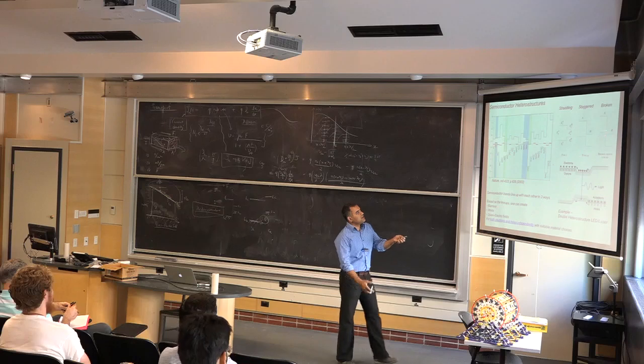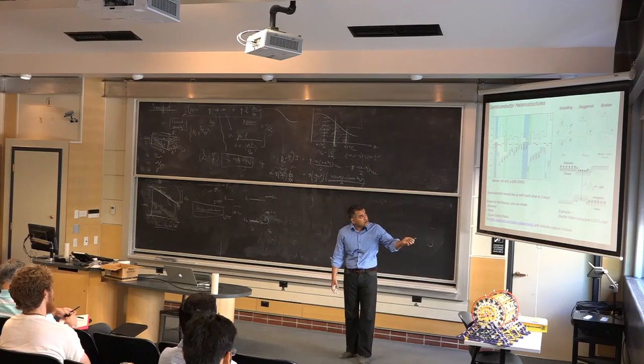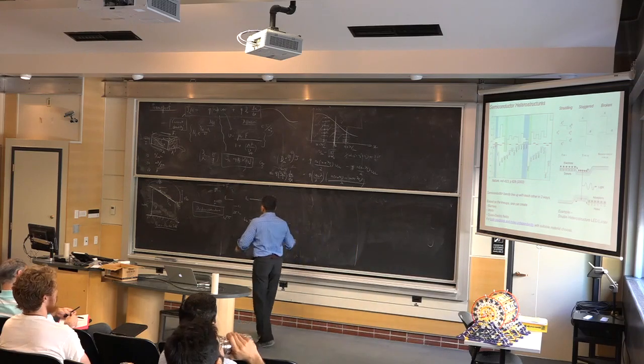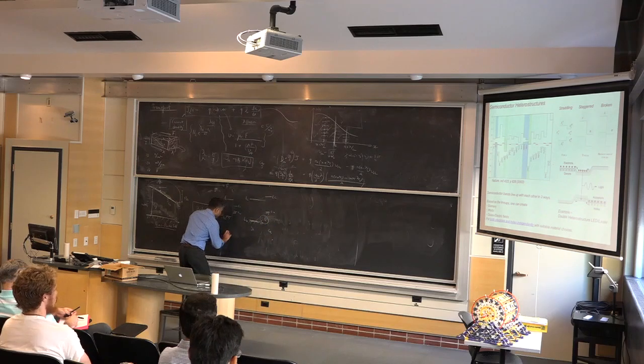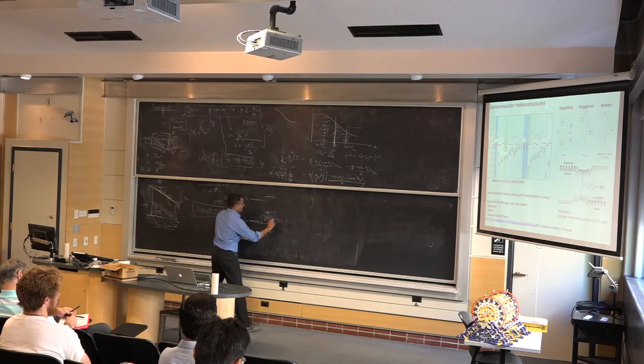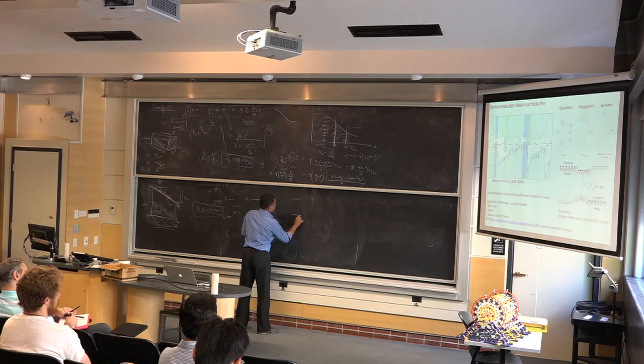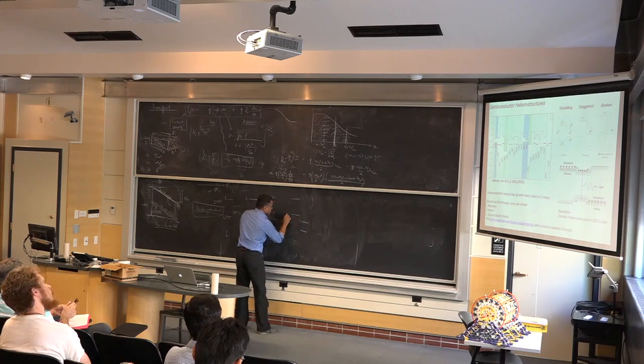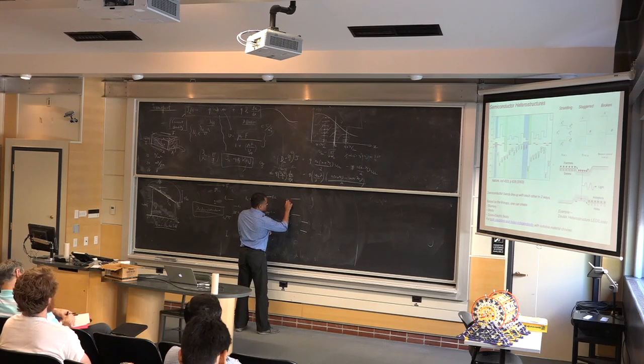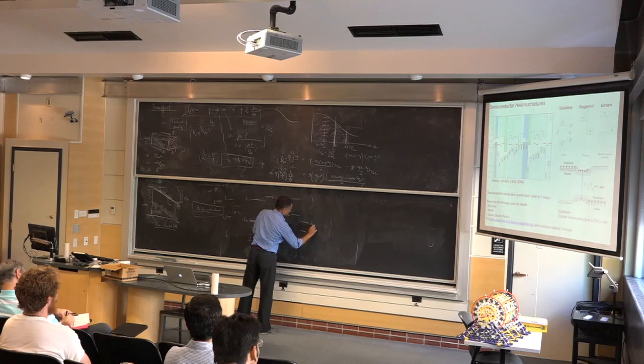And finally, you can have a very strange situation, which is called a broken gap material, where, so this is type 1, type 2, and type 3 is when the conduction band of the second semiconductor is below the valence band edge of the first semiconductor. That's a very strange situation, but you can have that as well.